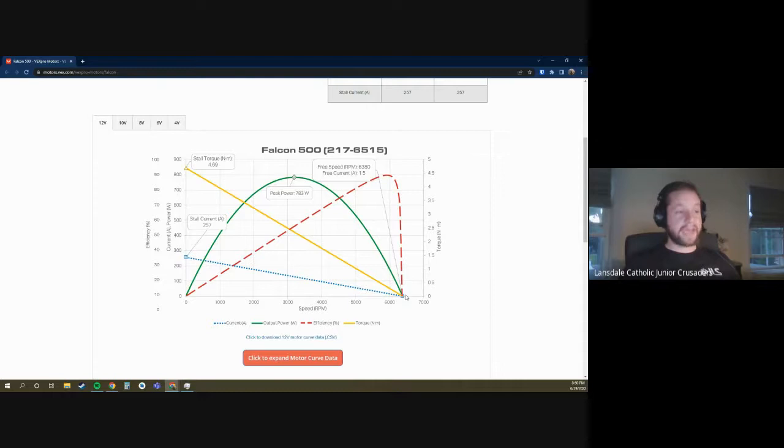But you'll see at that maximum speed, it provides, on this yellow curve, absolutely zero torque, which means it's not providing any power at all either. Even though it's rotating really fast, if the torque is zero, you're not providing any power to the system. And remember that equation: power equals torque times rotational velocity.